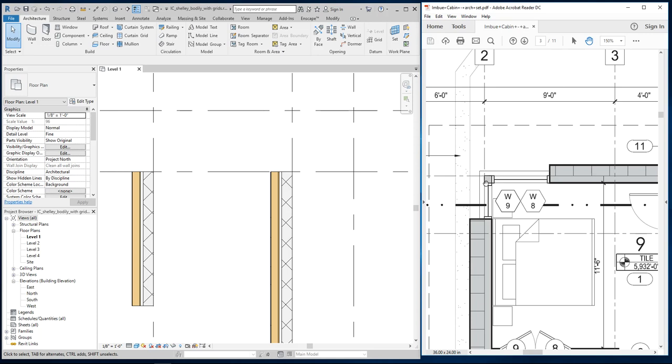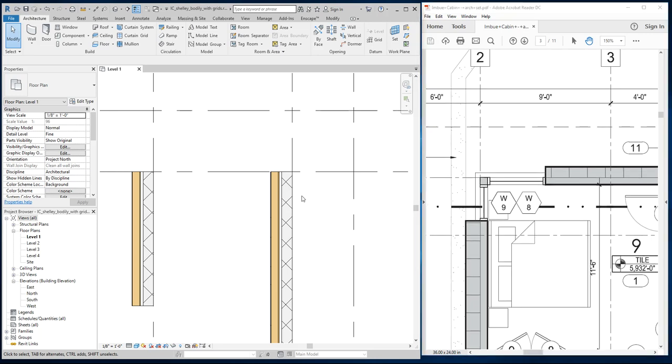Sorry, I said that maybe in reverse. What happens if your location line is center line and you change this wall type? It's going to distribute on both sides of the grid line. And those walls that you took a lot of careful time to lay out will be in the wrong position, right? So you'll have to realign them. Just something to keep in mind.